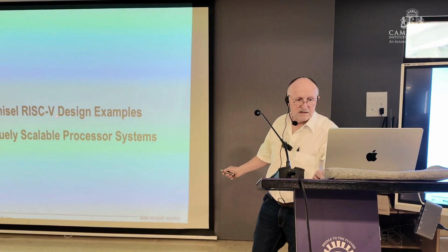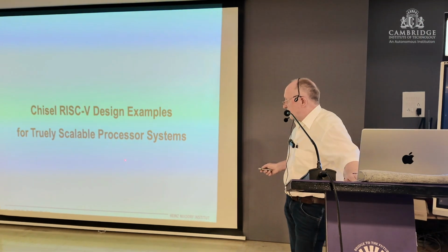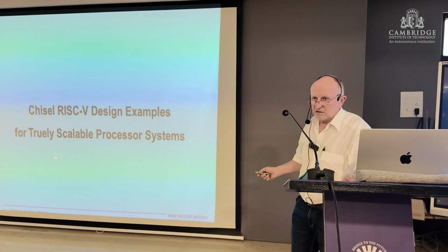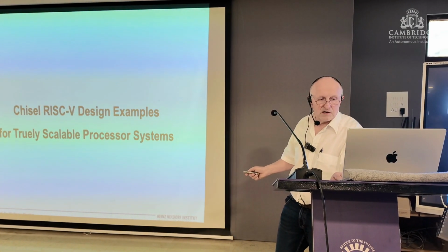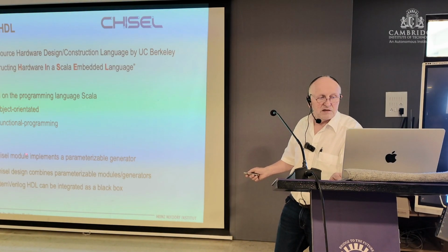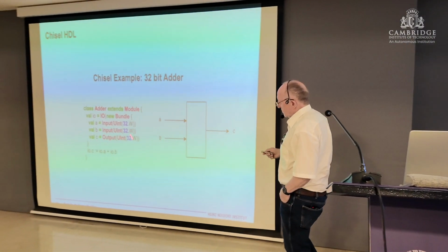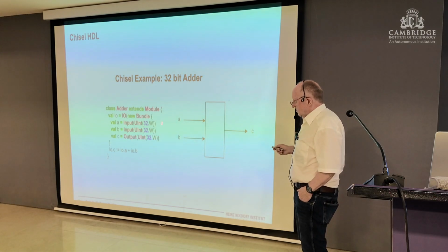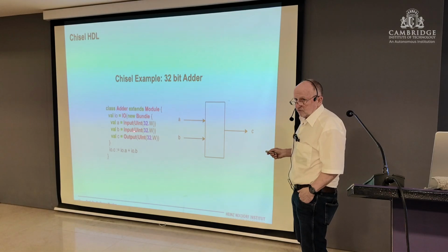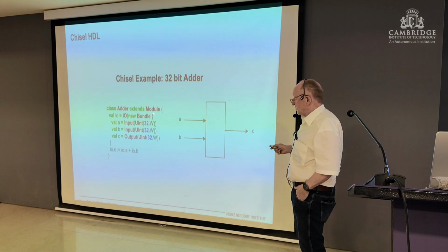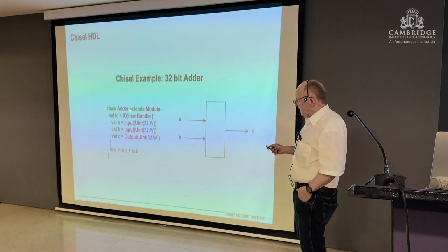Having said this, I would now like to give you some examples in Chisel, because nobody so far has ever seen a Chisel design. A Chisel example is written here. It's based on the language Scala, which is basically for software implementation, and this is some extensions on it. Here you have classes which extend modules.